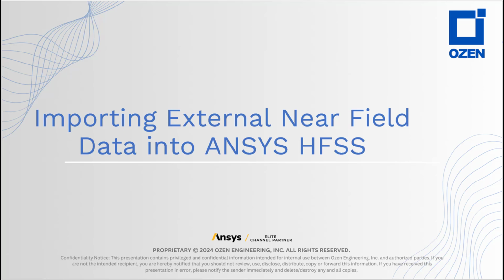In this demo, we'll show you how to import near-field data into ANSYS HFSS. Users may need to import fields whether calculated analytically, measured, generated by another tool, or received from a provider, and use them as a realistic excitation to perform different types of analysis.